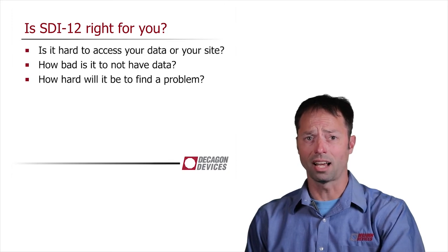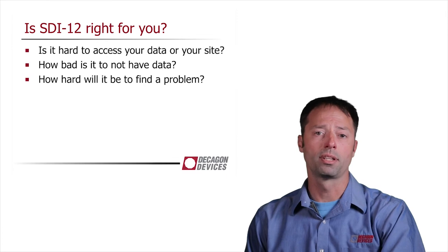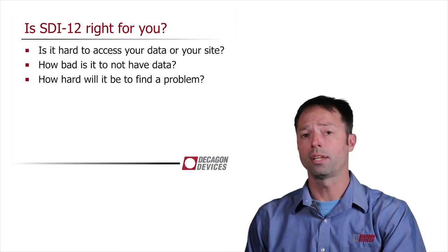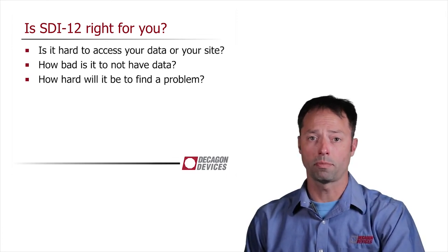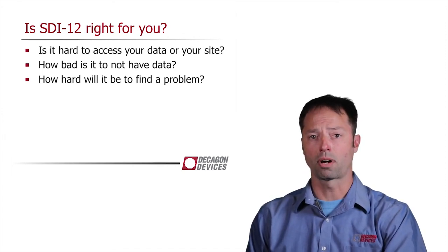and how bad is it to not have data? If you must have every single data point, then SDI-12 may not be right, just because if one sensor goes out, you may lose data for all of them. And how hard will it be to find a problem?